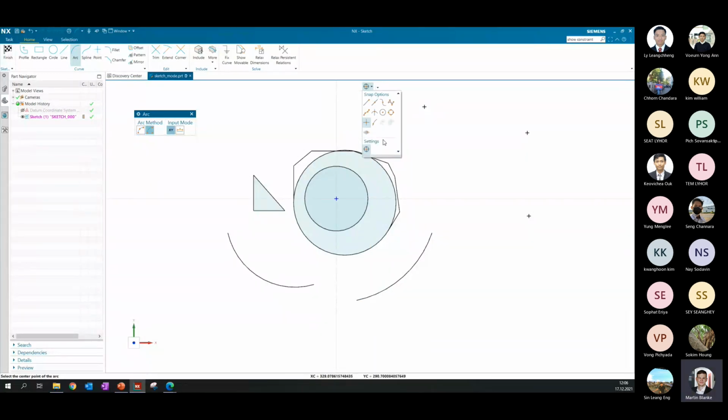Now I want to select a random point on my curve, so I unselect the existing point and I select the control point, for example. Or maybe let's do the midpoint, it's a better one. So now I want to select the midpoint of this curve, and as you can see here, I can select the midpoint of this curve.